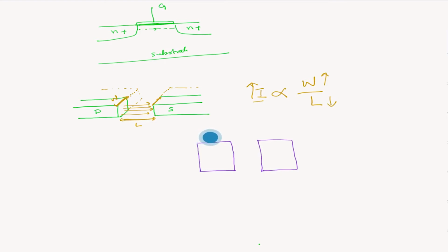This is, let's say, the inverter shelf. So we develop transistors with different widths. We will have one, let's call it inverter 1, with one value of width. We make another inverter with a bigger width, another one even more. So we have a variety of this inverter in a given library. Similarly, same thing with any NAND or any flip-flop. There are different versions of those cells, and each has a different width of the transistor.